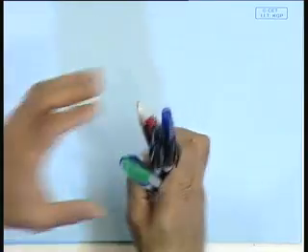But what ends up happening, because I'm doing sampling, I'm just picking up some items from this, and using those sampled items, I do my inspection and I decide the fate of the full lot based on the results of the sample here. I might be rejecting a good lot. It's very possible that my sample by chance turned out to be a bunch of defectives, and I end up rejecting an otherwise good lot. Now, this is a loss to the supplier. This is the rejection of a good lot.